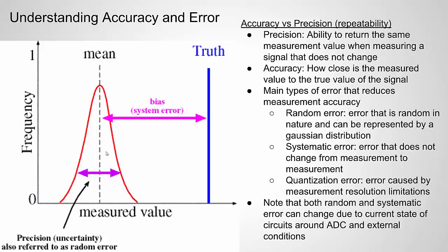But let's say sometimes you make measurements and the Bluetooth is transmitting, but sometimes you make measurements and it's not. So you'll see the error from the Bluetooth signal come and go in your measurements. Often error is not that simple as constant systematic or some kind of constant random value. If you have a complex design and you made 100,000 measurements and you plotted those measurements, you might see multiple Gaussian curves at different positions, because you have different types of systematic and random error depending on what the circuit is doing at that time.